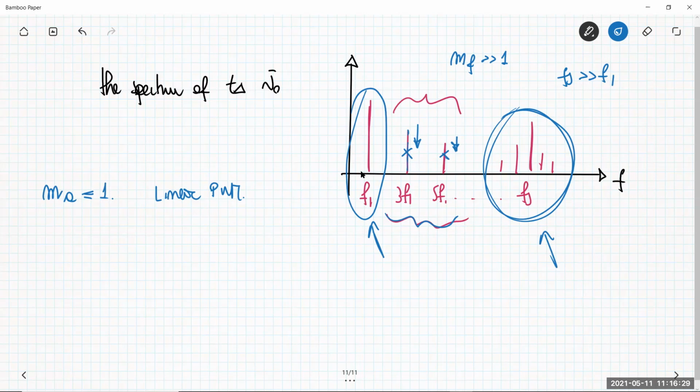The information is amplified linearly, so I have the same information content at the output. Basically I have the same spectrum amplified at the output. And then I have to demodulate in order to extract exactly the information I need. This is basically my linear process: modulation, amplification, demodulation. I saw this several times.